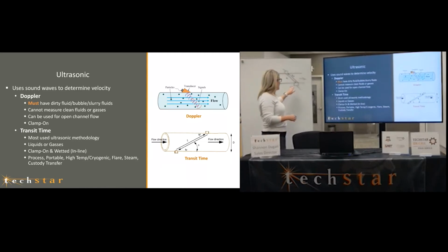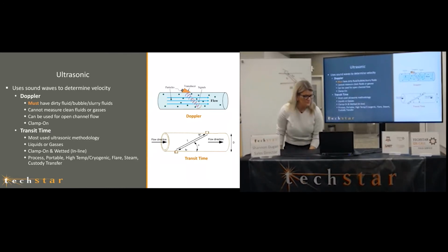So as the flow increases, the delta T gets bigger. The time in between the sending and receiving gets bigger. Similarly, if you have no flow, this delta T is going to be 0 because it's going to be exactly the same amount of time to go up and down because there's nothing inhibiting or pushing the signal faster.